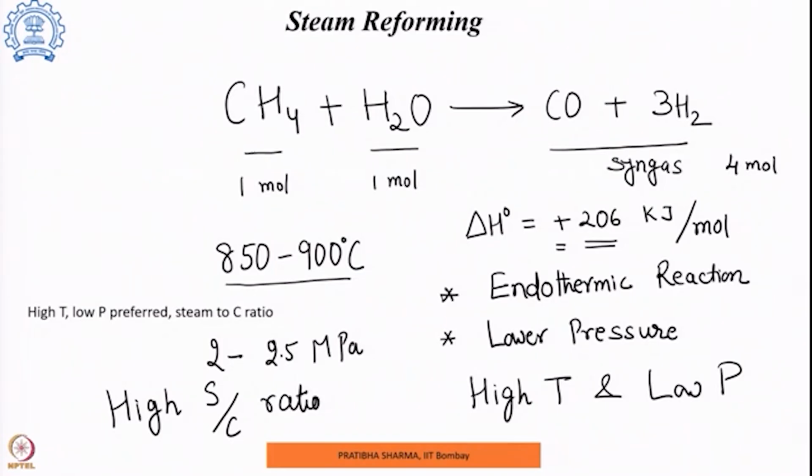So, the coke deposition can lead to deactivation and several other challenges. It can deactivate the catalyst, can deposit onto the surface of the catalyst, reducing the active sites, and can create hot spots because of that. At the same time, the deactivation of catalyst can lead to higher tube wall temperature.